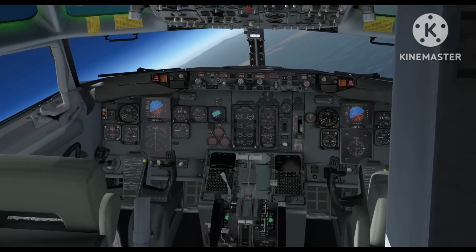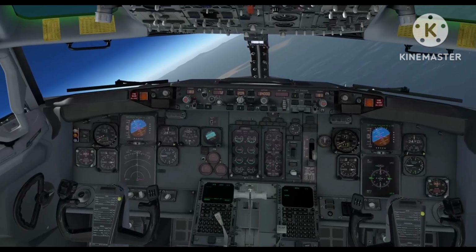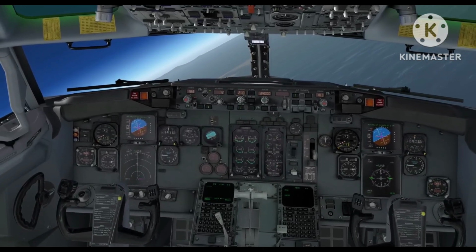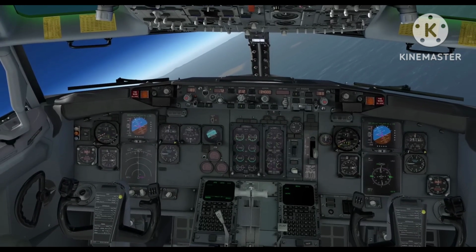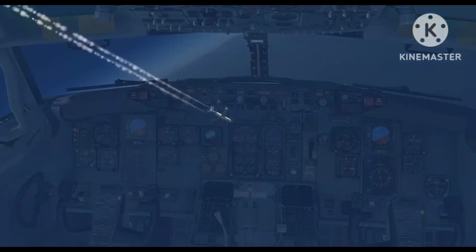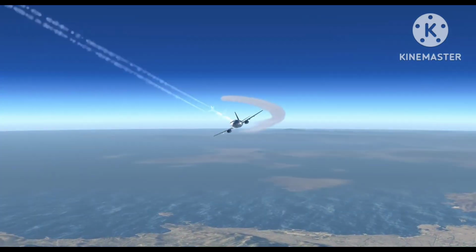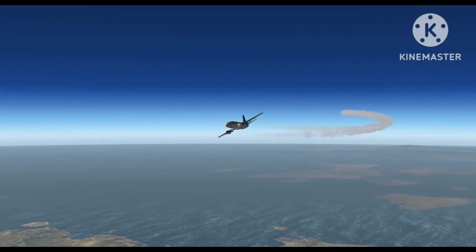In the Boeing 737 aircraft, both warning horns produce the same sound. The critical difference lies in their context. The takeoff configuration warning horn should only be audible on the ground, whereas hearing it in the air indicates a cabin altitude warning. Modern 737 aircraft now include visual indications for these warnings.